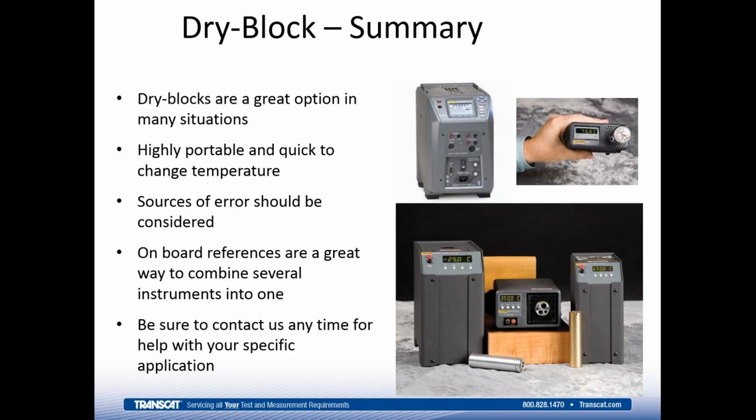So in conclusion here, great option for doing calibration work in a lot of different situations, especially where the environment needs to be clean or you need it to be portable. Get to places that are hard to reach to perform your calibration. It's great. If you need to get to a specific level of accuracy that's maybe better than just 1/10 of a degree, then you want to use an external reference probe.